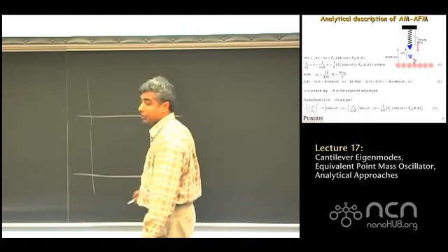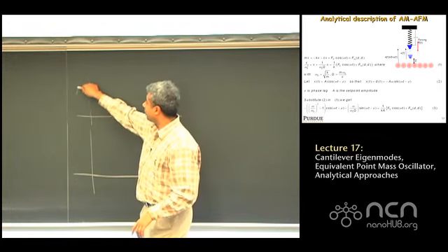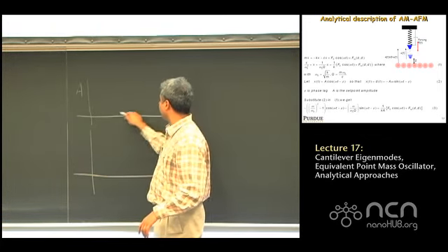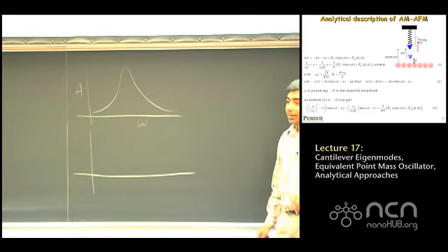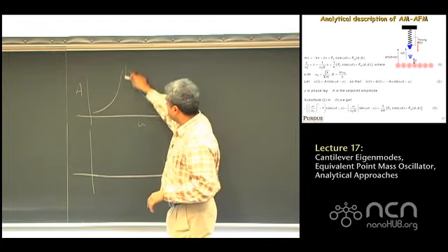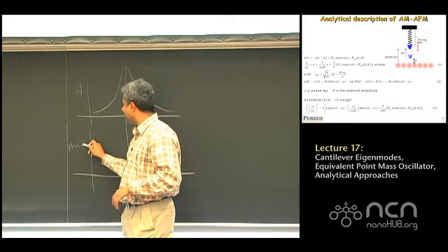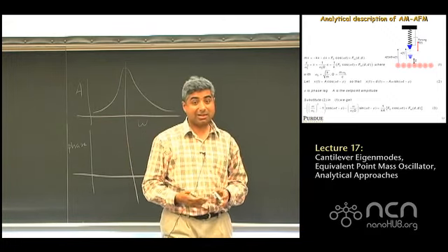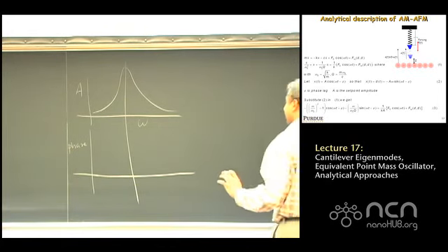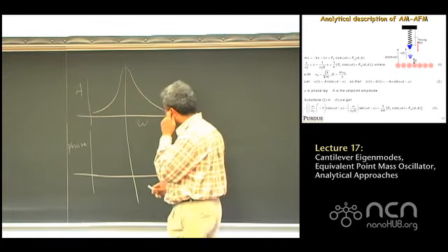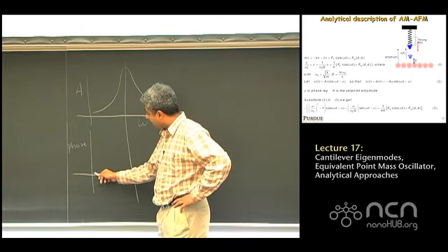do a tuning curve. So you withdraw from the surface, do a tuning curve about that resonance, and you plot A versus frequency, right? And you get this resonance curve, which you want to operate on. While you do it, make sure you plot the phase, or whatever they call the phase. And nobody tells you that it's a phase lead or phase lag. They're just going to say phase, right? That's all they're going to say. You plot that. And if you find that it does this,